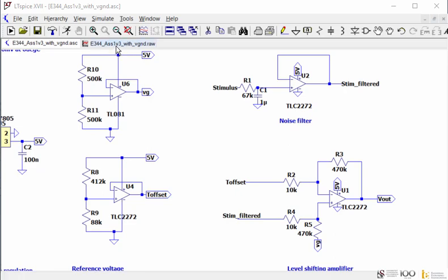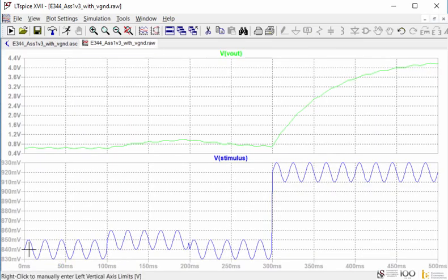Right, so now that it's simulated, let's just recap quickly. I gave it an instruction to jump 1 degree, jump back 1 degree, and then jump the full range to the maximum degrees. So from 34 to 42, 8 degree jump there. So if you consider this output, at the bottom is the input, top is the output, you can see that there's a wavy signal coming in here. It has a response, so it's steps. So if you look at 100 milliseconds, and over here, it should have reached that point already. Goes down slowly, goes up, jump here.